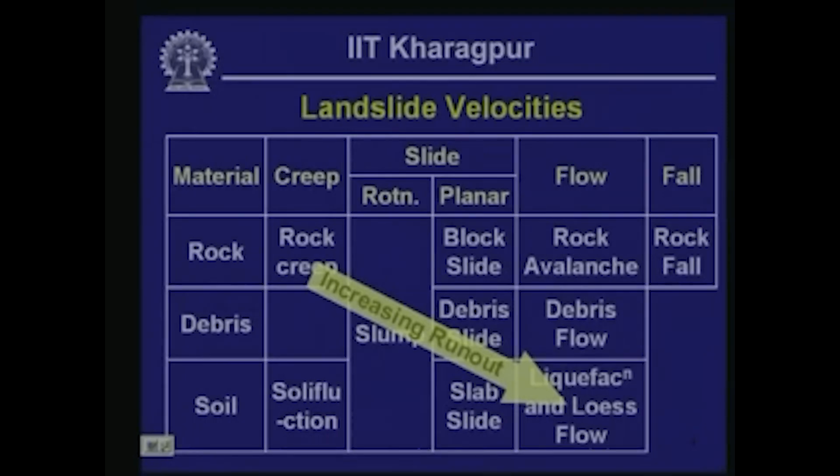On the other hand, when you are talking about rock creep movement, then the distance traveled by unstable mass is going to be quite small. Rock creep is going to affect areas which are typically less than a meter in scale in horizontal distance, whereas mud flow, for example, or liquefaction flow slide could affect several kilometers downslope from the location where the flow was originally triggered.